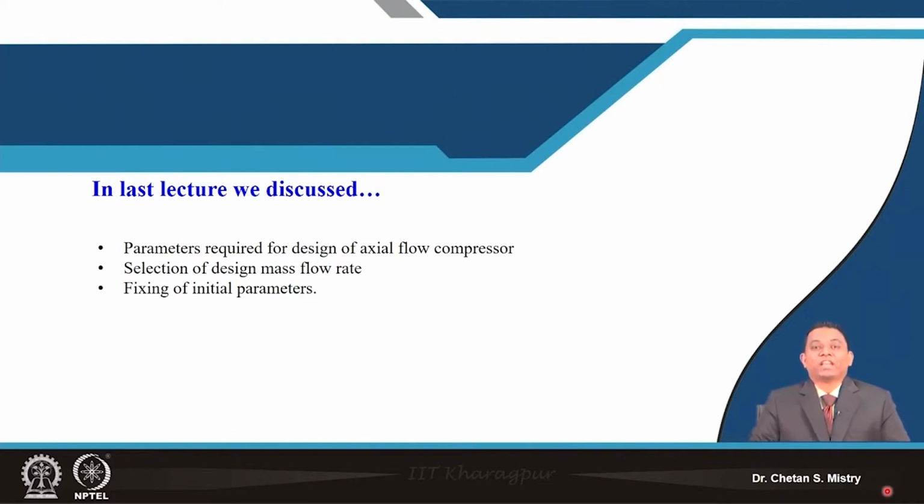For a fighter or supersonic aircraft, the expected thrust will be different from the takeoff thrust, so the mass flow rate for the design will be different, in line with our expected performance for the turbomachinery. So selection of this design parameter for supersonic aircraft is done at the supersonic cruise condition.